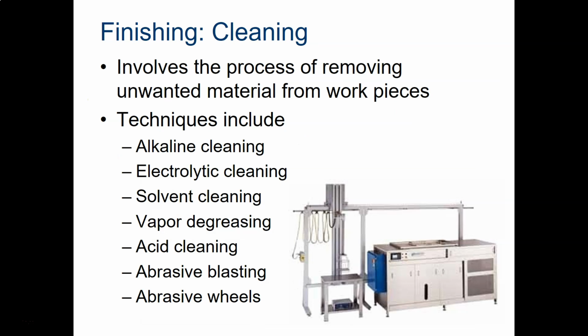Another finishing process to consider is cleaning, which is typically performed in preparation for further processing. The unwanted material may be a soil or grime, some grease, or a scale or stains, blemishes, or even a corrosive deposit. Alkaline cleaning employs alkaline solutions. Parts are soaked or sprayed to promote the cleaning.